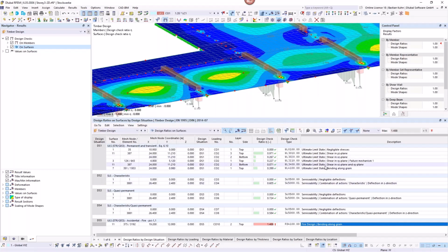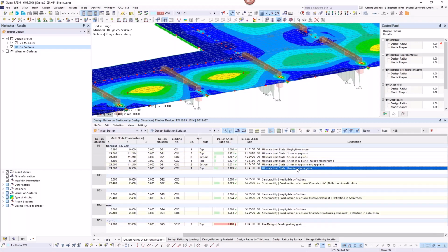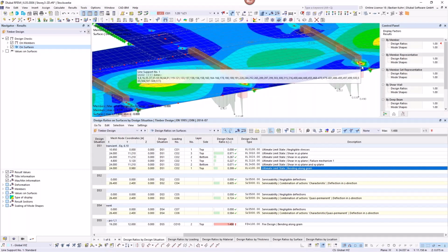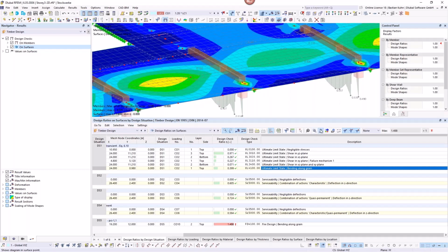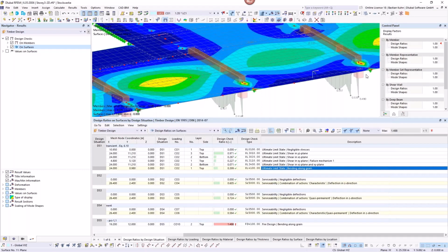Before we do that, we also take a look at the other loadings inside here. The shear for the punching through area is designed in here on this part. That's the usual punching through area that you want to take a look at. And we can maybe also take a look at the stress over the whole section, because I think that's always nice to see. And you see for the bending how the stress is transferred into each layer of our section or our surface.